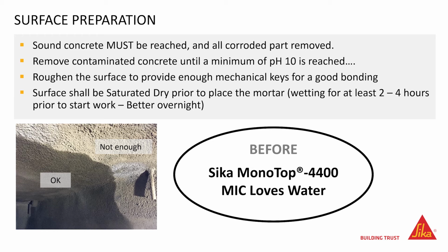The surface shall be saturated dry prior to placing the mortar, wetting for at least 2 to 4 hours prior to starting work, or better overnight wetting. The picture on the bottom shows part of the surface sufficiently pre-wetted, and a part not wetted sufficiently.